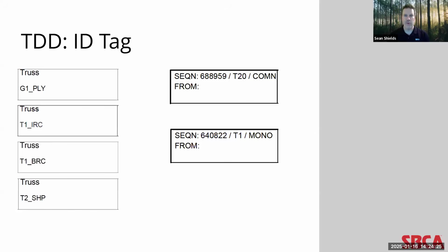Again, the reason why this truss tag is used is to help quickly locate where this particular individual truss may be found within the overall roof or floor system on the truss placement diagram. Just like with the job number, the truss tag can also be used effectively by the building designer or the building official to quickly identify a particular truss that may have an issue.